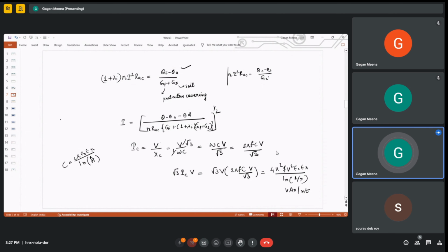So there are overvoltages due to switching, and the interruption of capacitance current gives rise to these overvoltages. There is also the Ferranti effect. If a significant portion of a transmission distribution system is underground cable, then there is a rise in voltage at the load point, especially during no load or lightly loaded conditions.